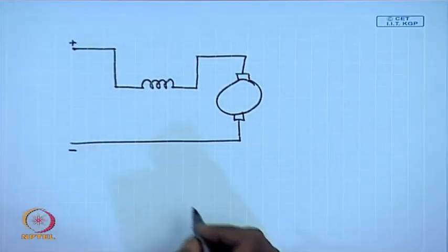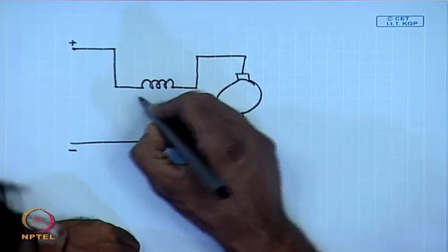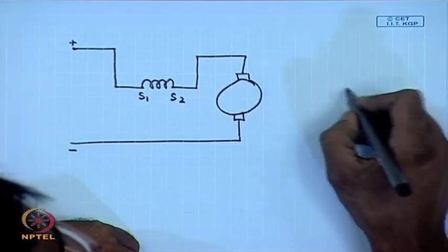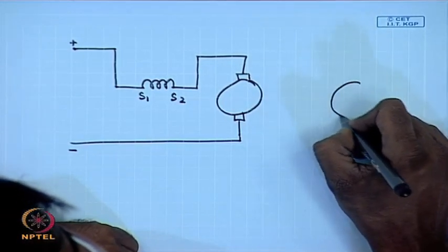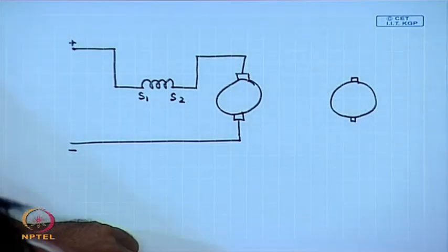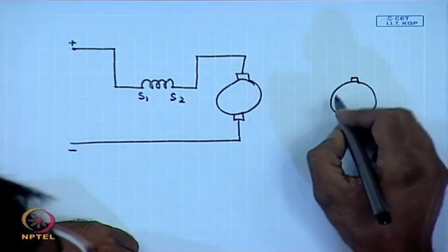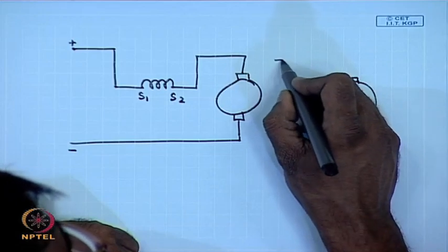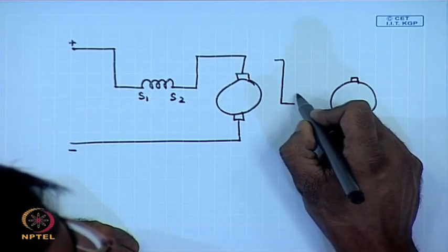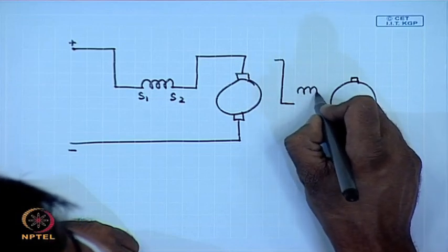In order to generate reverse torque, one would need to reverse the connection of the series field.